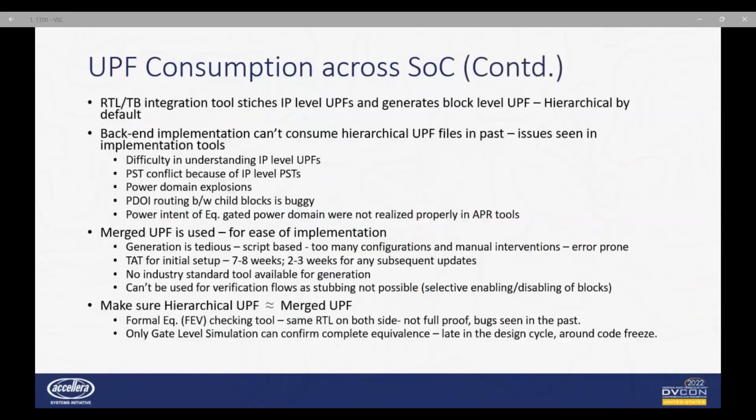The reason for using merged UPF for backend implementation is because in the past, downstream implementation tools could not easily consume hierarchical UPF files. There were many limitations. Backend tools could not properly understand IP level power intent. Sometimes strategies were not properly realized and they were dropped. There are PST conflict issues also because of PSTs in the child UPFs. This results in dropping of PST tables, which in turn reflect a wrong power intent.